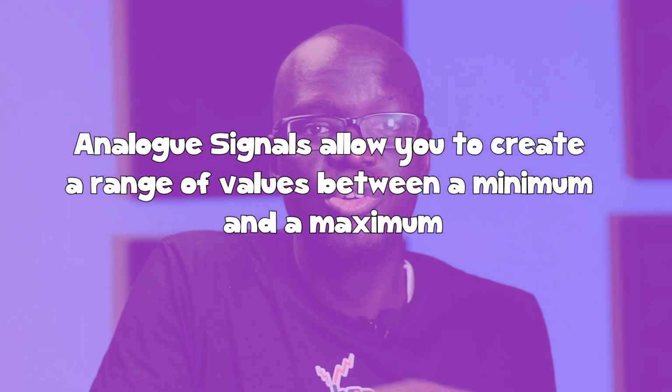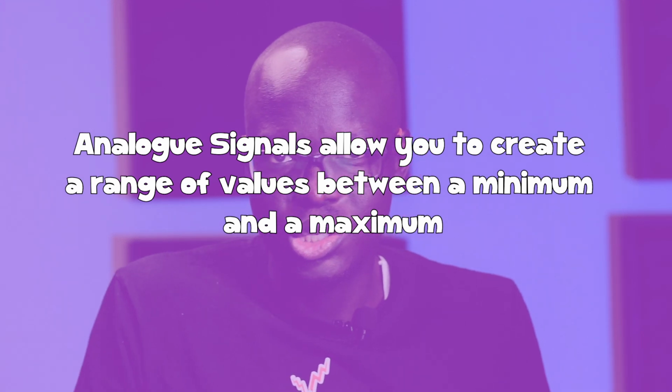However, if you are trying to create a different sort of application or a different use case, then you might want your LED to be able to go from 0 to 100 in terms of brightness. For a digital signal, you'd either have 0 or 100. You'd not have anything in between, which means you cannot increase brightness, you cannot increase speed. However, in these scenarios, you can use an analog signal. So analog signals allow you to create a range of values between a minimum and a maximum. So if your minimum is 0 and your maximum is 100, an analog signal can let you have a value of 5, of 10, of 20, of 30, or 100. Whereas with digital, you'd either have 0 or 1.